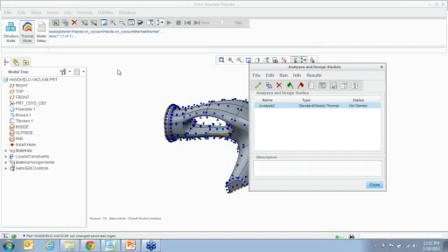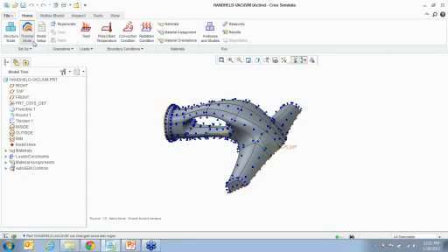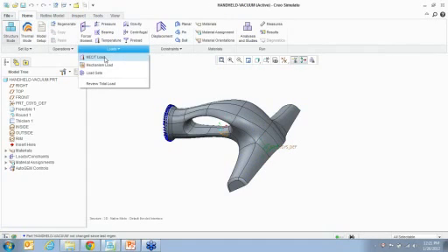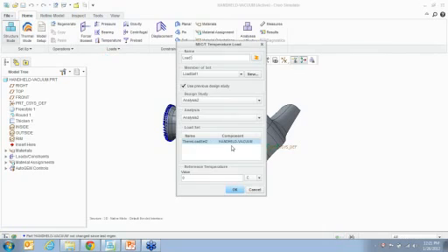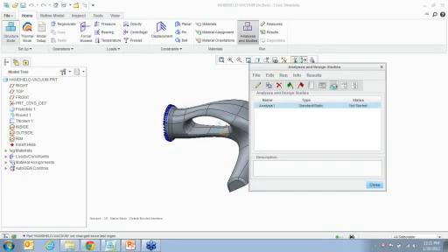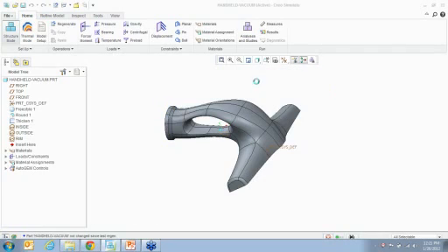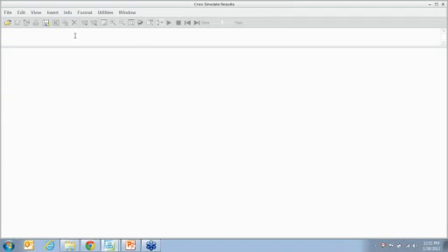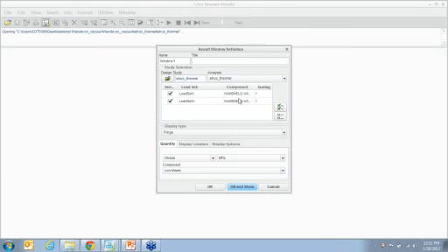So we can go back to structure and say I want to input a thermal load from the Mechanica thermal analysis that I've just run, and I say okay, the local reference temperature is 30 degrees, and I can add this thermal load and run a regular static analysis. This will give me a result showing what happens when a structural load as well as a thermal load is acting. So let's look at what happens only when the structural load is acting.